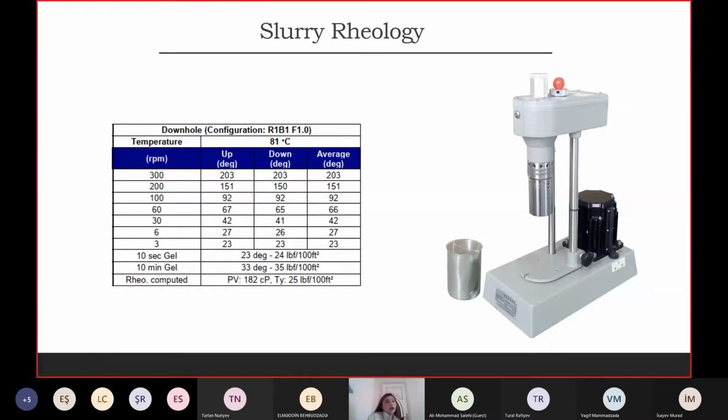And when you pump cement slurry, we are pumping mud, spacer, slurry, and this should have a hierarchy. Look, for density, we have a hierarchy. Mud density should always be lower than spacer, and spacer lower than slurry.